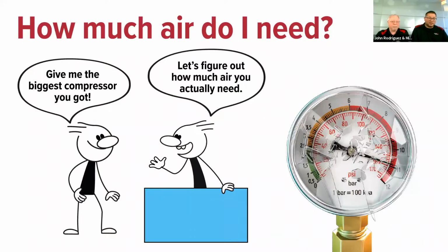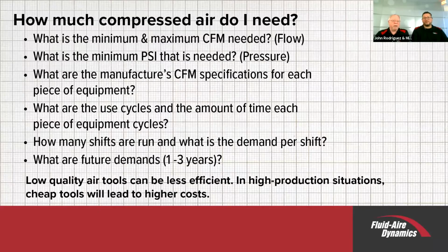So now that we know that it's expensive, how much air do I really need? Well, jump to the next slide and we'll talk about it. You should know what your minimum and maximum CFM needs are. It's more important to know the maximum, because you don't want to run out of air, obviously. Minimum would be something that, if you have a weak compressor, you might want to run.